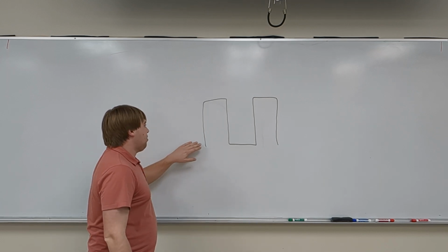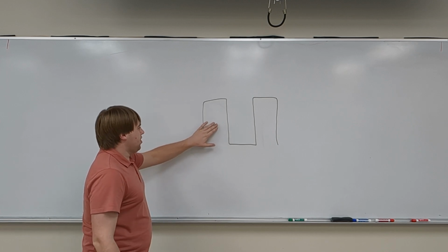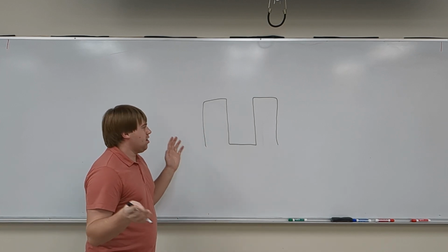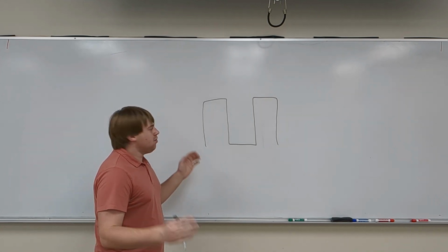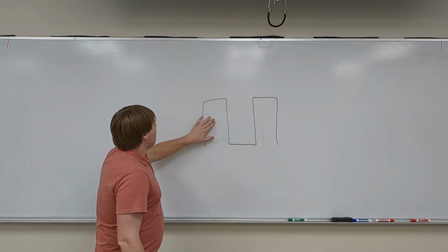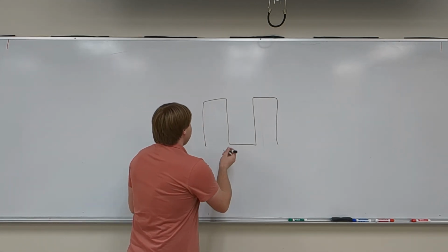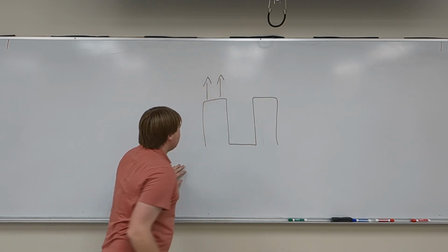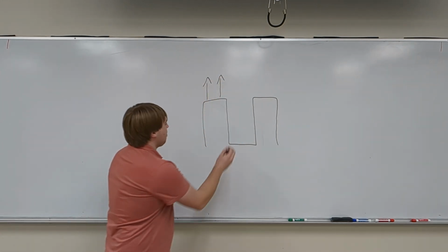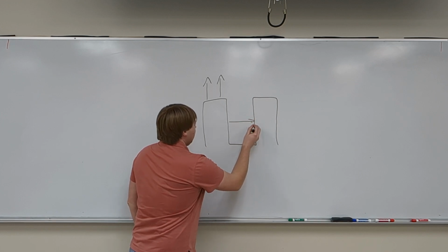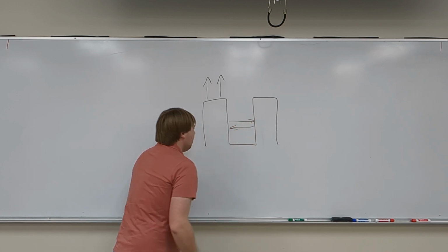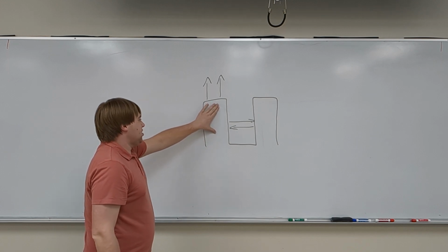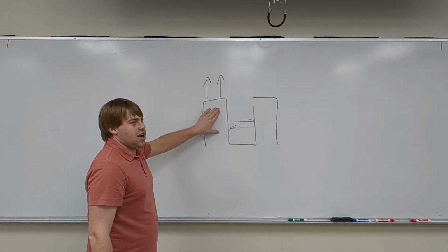And after learning about radiation, we realized that because all things emit radiation at any temperature above absolute zero, which these buildings are, I hope, we have radiation that is emitted. Some of it can go to space, and then it leaves. But some of it gets radiated right back to the other building, and then back to the other building. That radiation can't leave. So that energy sticks around until it's convected to the air.